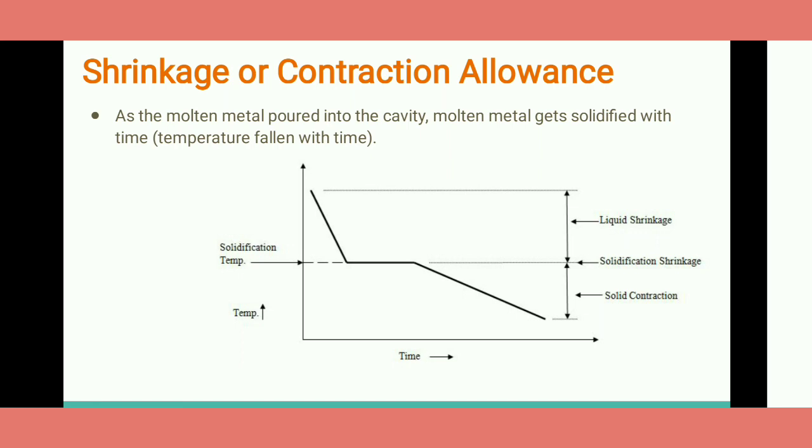So here it is the molten material. Once it is filled inside the mold cavity, it will cool, and as the temperature continuously decreases with respect to time, some part of it becomes semi-solid, or there is a formation of dendrites. Because it is completely liquid, and with respect to temperature the liquid tries to become a solid phase.